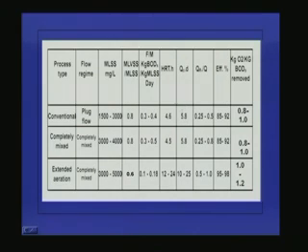See the difference, here HRT is varying from 4 to 6 hours and theta c is varying from 5 to 8 days. The recirculation ratio is 0.25 to 0.5 and the efficiency varies from 85 to 92%. For kilogram of oxygen per kilogram BOD removed, usually we have to provide 0.8 to 1 kilogram of oxygen. So, from this we can find out the horsepower required.